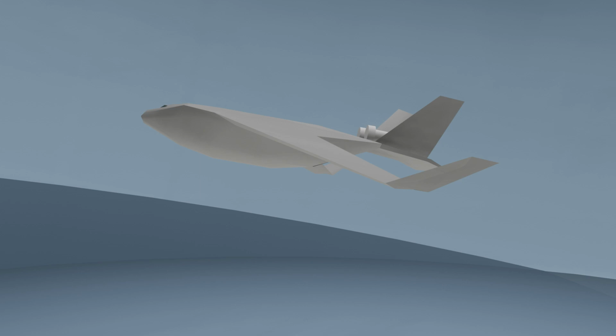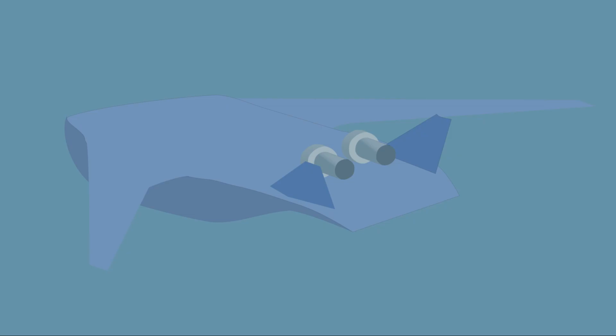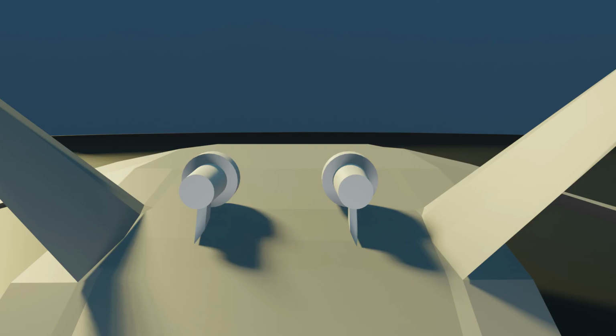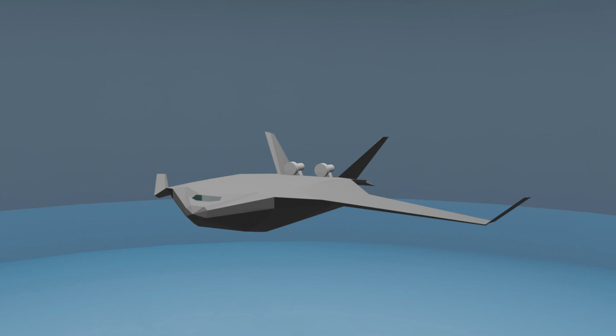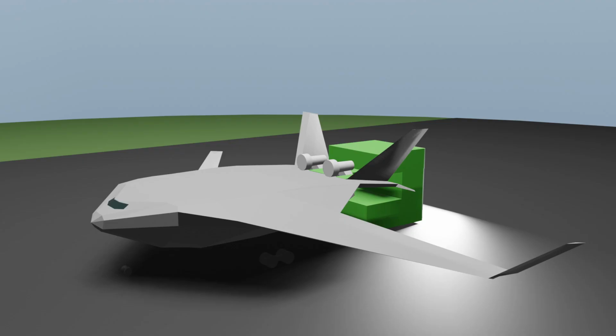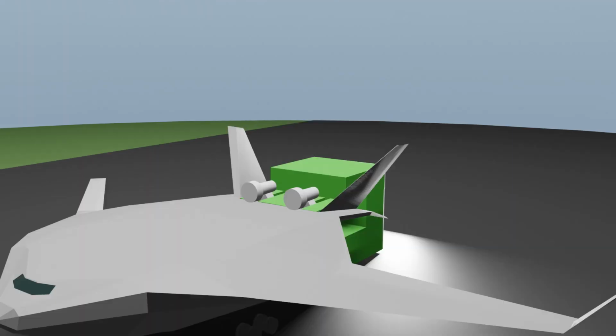The problem of stability and control is not a simple one, and if it can't be addressed, this aircraft can't work. The engines could be mounted at the back of the aircraft above the fuselage, with the vertical stabilizers canted somewhat outwards. That would mean that a significant part of the noise coming out of the back of the engines would be reflected off of the top of the aircraft and off of the vertical stabilizers upwards, reducing the noise signature at ground level. A specialized platform would have to be built for access to the engines, but it can be done.